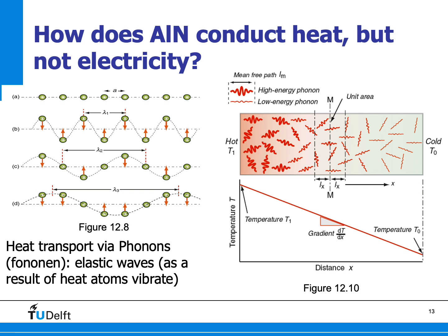And these phonons have some mean free path over which they can travel through the material, and by traveling through the material they basically conduct the heat. So the heat is conducted through the material via these elastic waves, which we'll also call phonons, or in Dutch, phononen.